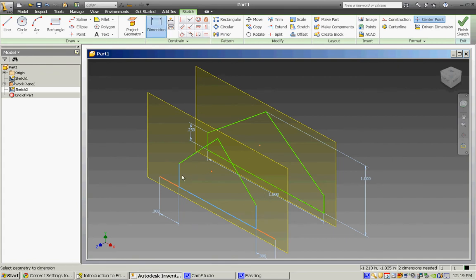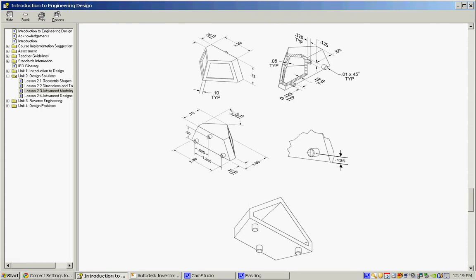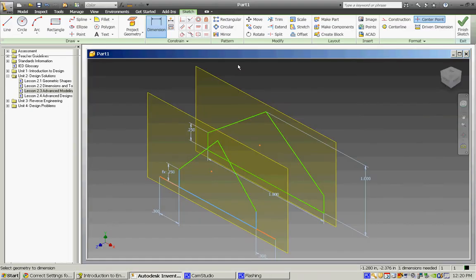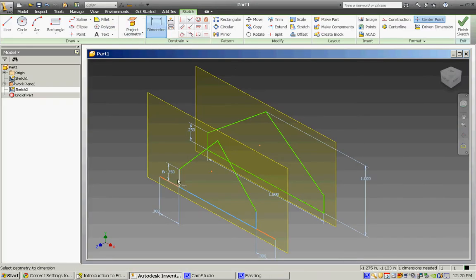Now what I'm worried about is this, how high this is. They don't tell us, but they'll give us an angle. Let's take a look at the beginning. The angle is 50 degrees from this straight line to that line. Therefore, what's its supplementary angle right here? It's got to be 130 degrees. So I will dimension the distance for the angle from there to there. It should be 130. We can check this one, but it probably won't let us drop it. So we know that it's correct.